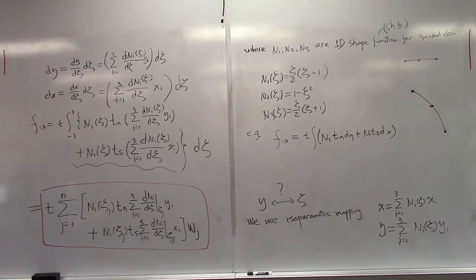Okay? Now, there's a third possible contribution, which is from the essential boundary condition. That again needs some special treatment here, and for some reason it's not in the textbook. It is not given here, but essentially it's done the same way, because it involves those D matrix and B, so it's very similar to the calculation of the element stiffness matrix.